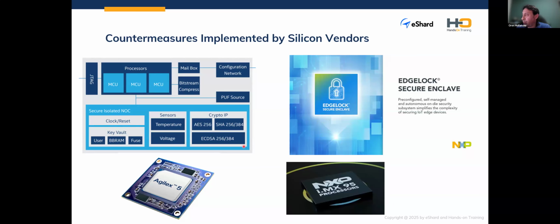So just a few words, the NXP i.MX95, and again, just the use case, uses the EdgeLock secure enclave. This is, just for your attention, kind of an autonomous subsystem with its own CPU, RAM, ROM. It's physically separated from the main Cortex-A55 cores that you can find on the device. It contains as well on-chip glitch detectors that monitor the VCC line for any transient drop faster than, for example, 5 nanoseconds.